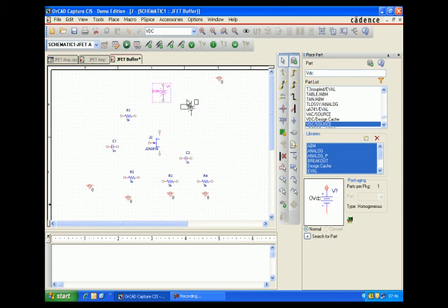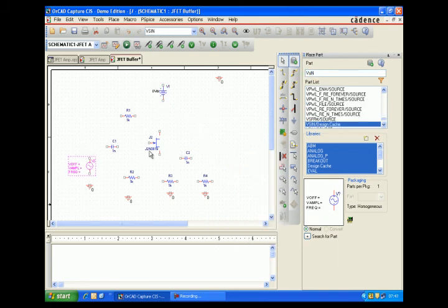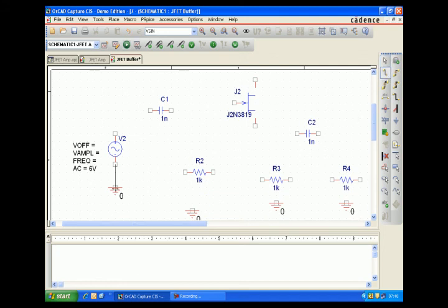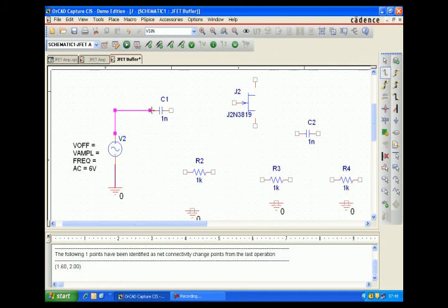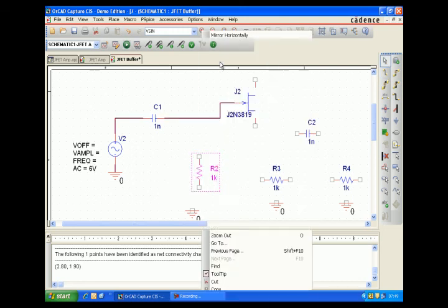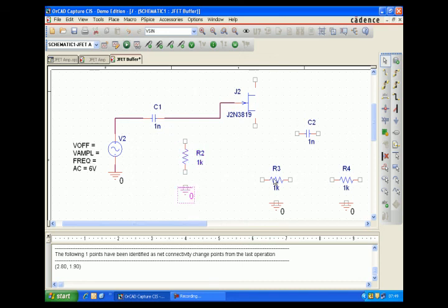Keep all the components, the Rs and Cs. Make a voltage divider, C1, CC1, 0.1 microfarad. Rotate the resistors so that they make a voltage divider near the base.